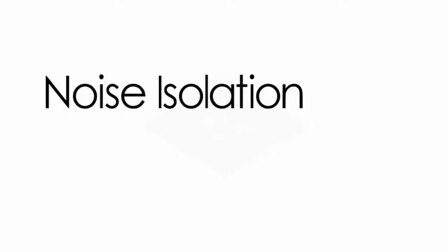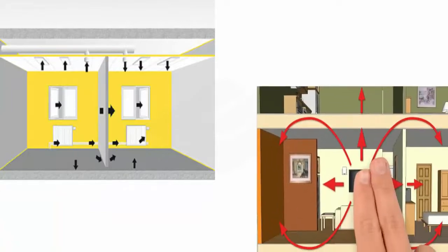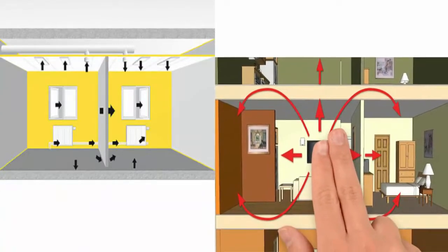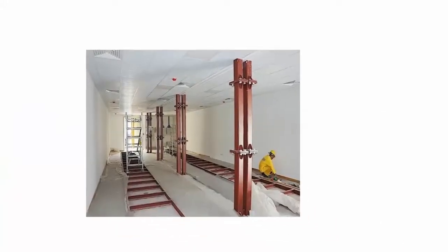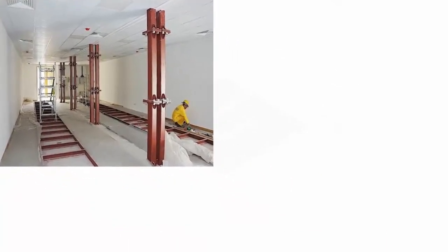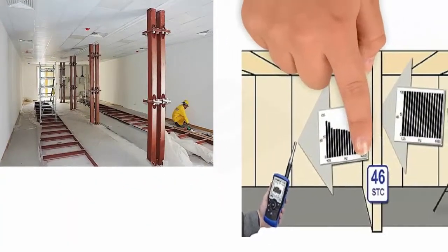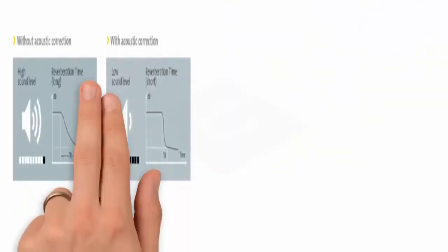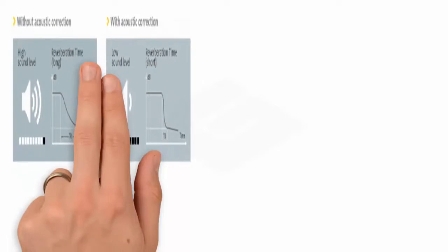Noise isolation class of walls. NIC, noise isolation class, is a single number expressing the actual degree of sound control between two adjoining areas measured at various frequency levels, pitches, on-site in a building, and is commonly referred to as a field test. The higher the number, the better the control, leading to improvement in acoustic comfort.